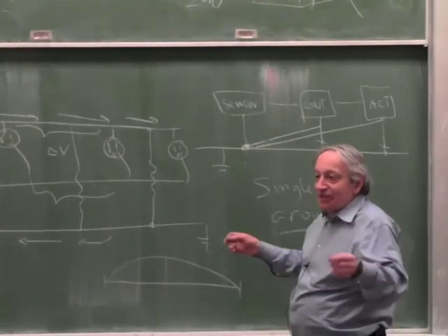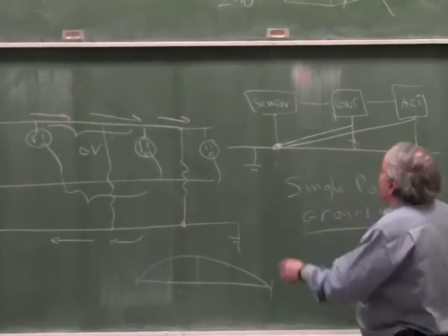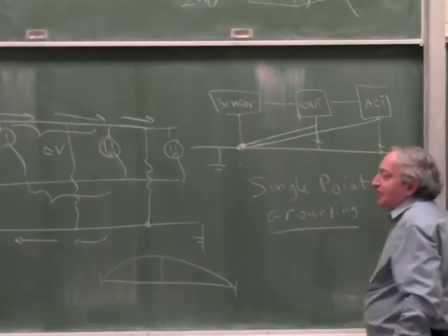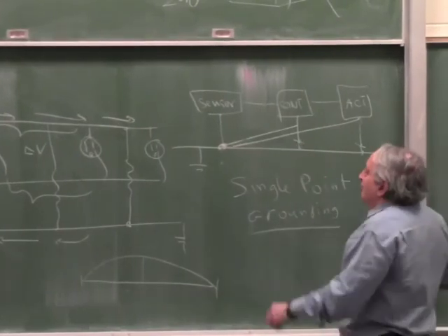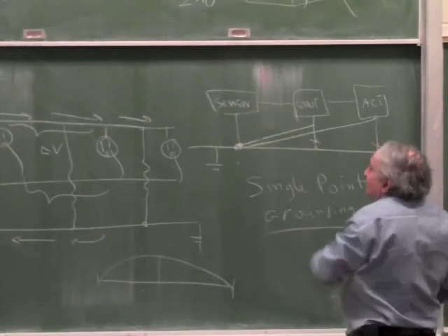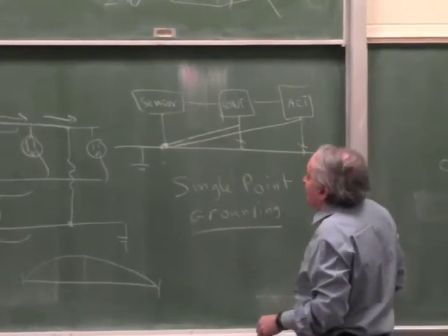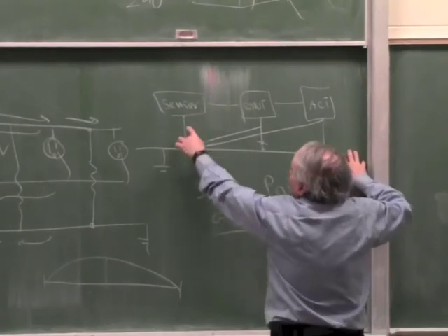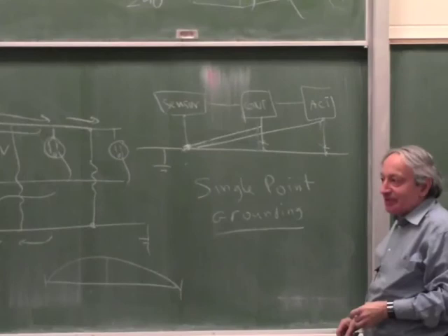Right? Just like a string of a violin. It can move in the middle and not at the ends. So if these wires become a significant part of the wavelength, the system doesn't work well. And you're better off trying to ground the shortest path anywhere. Okay, so another style of grounding is, especially if you have a big metal enclosure, ground everything to the metal in the nearest path possible.